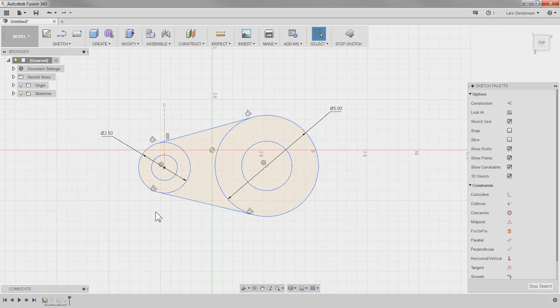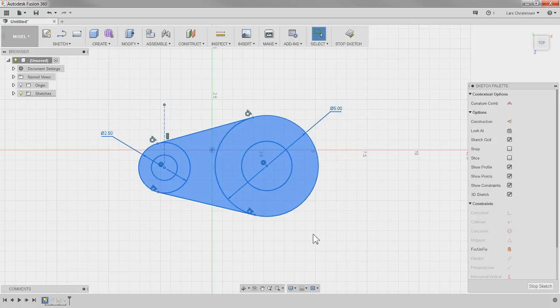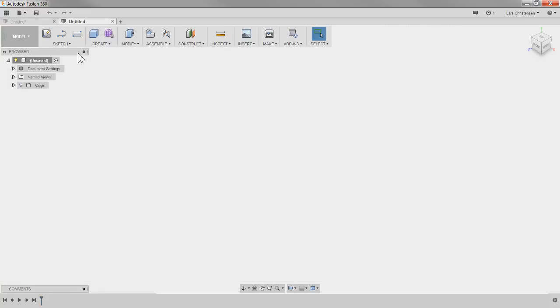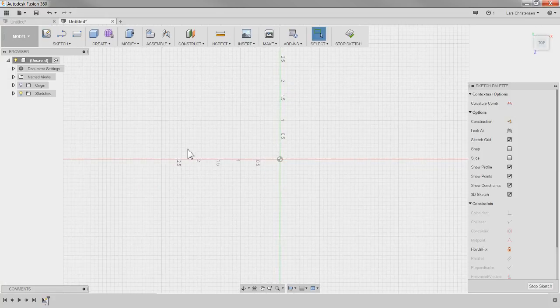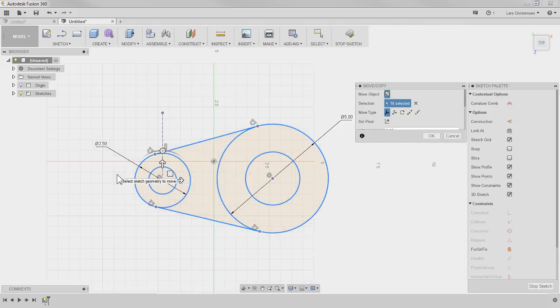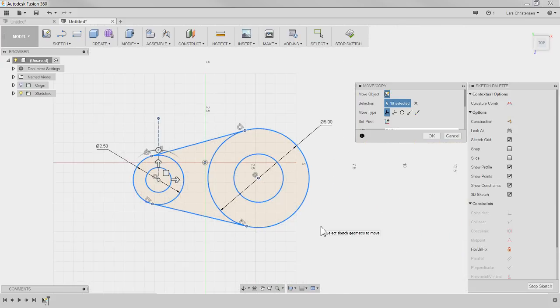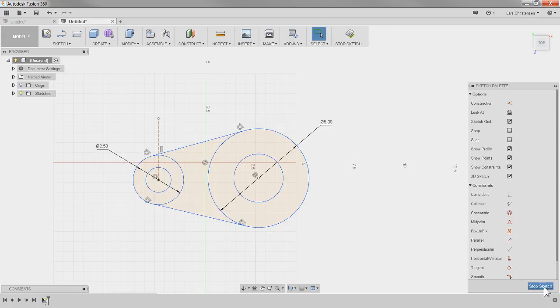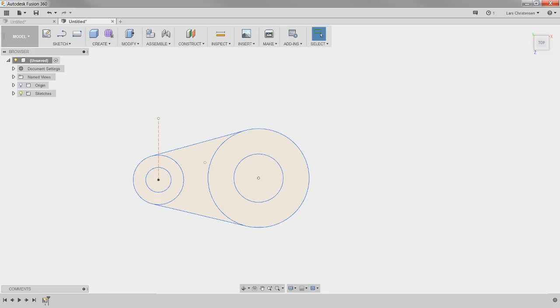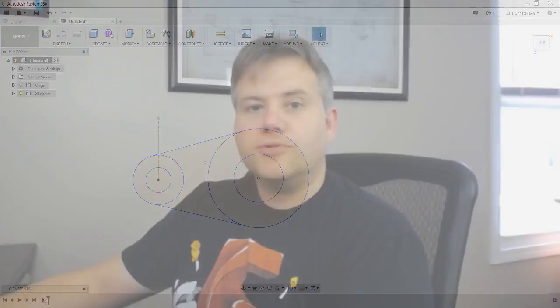But what I wanted to show that I think is probably the coolest thing is that you can actually also select a sketch, and you can do a Control C, and then on the new fancy plus sign up here, you can go in on a new part, open a new sketch, and you can actually Control V that whole sketch into another design. I know that there's definitely some people that are going to be excited that you can do that. So you're working on kind of like one layout, and you can go in and work with the other. So Control C and Control V are definitely some you need to know about, especially when it comes to the sketch there.